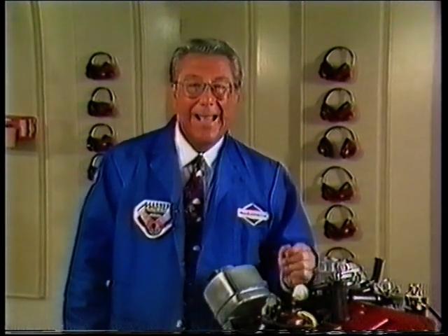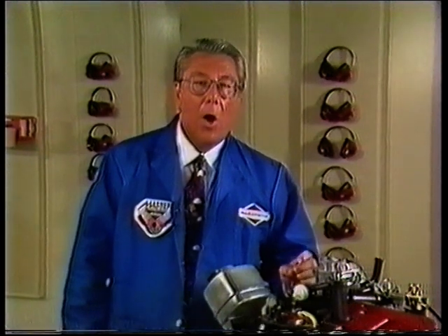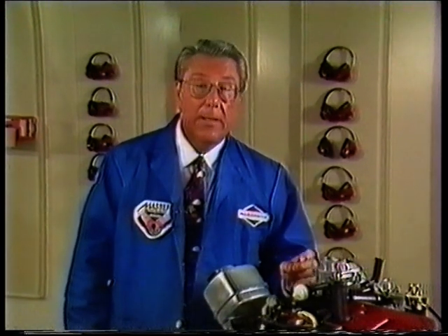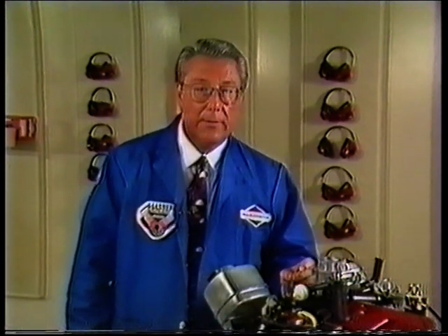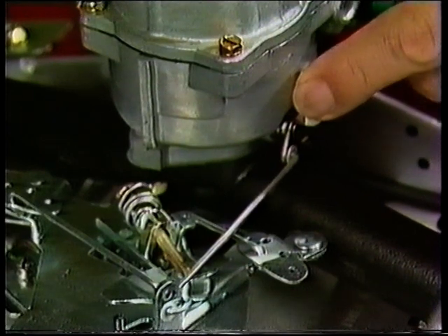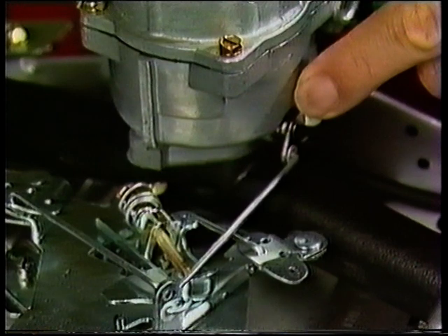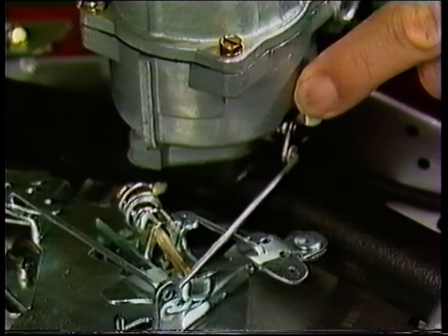To separate the governor system from the carburetor at governed idle, hold the throttle plate linkage against the idle stop and increase the idle speed to the governed idle specification. If the engine runs well without any hunting or surging, return the engine speed to the proper setting.